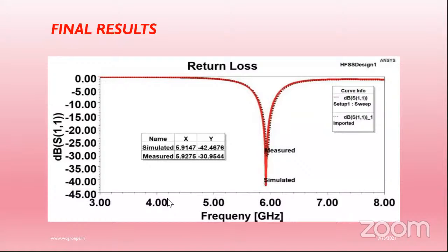If you want to find the efficiency of the antenna, the simulation characteristics also include efficiency characteristics. Otherwise, you get gain divided by directivity into 100%. So the gain value divided by the directivity value into 100% gives the exact percentage efficiency of that antenna.